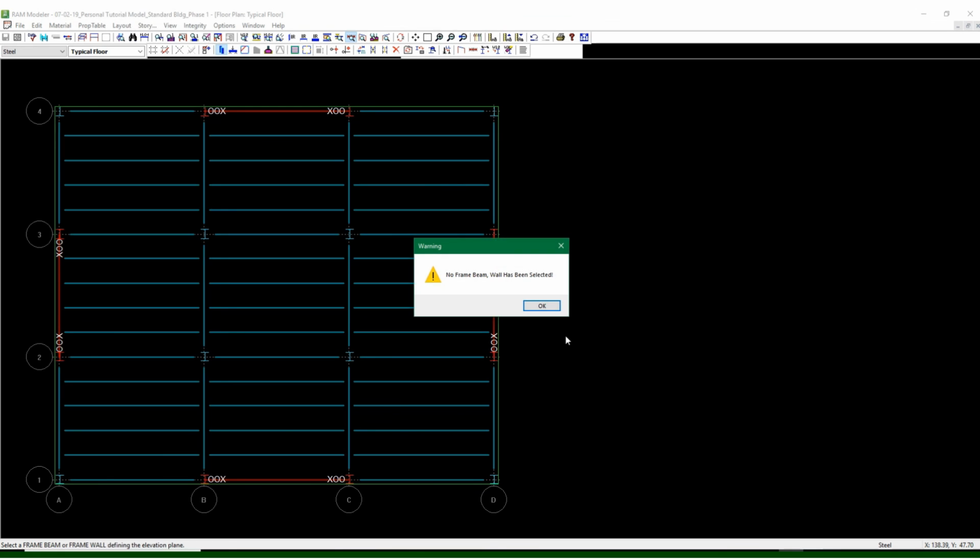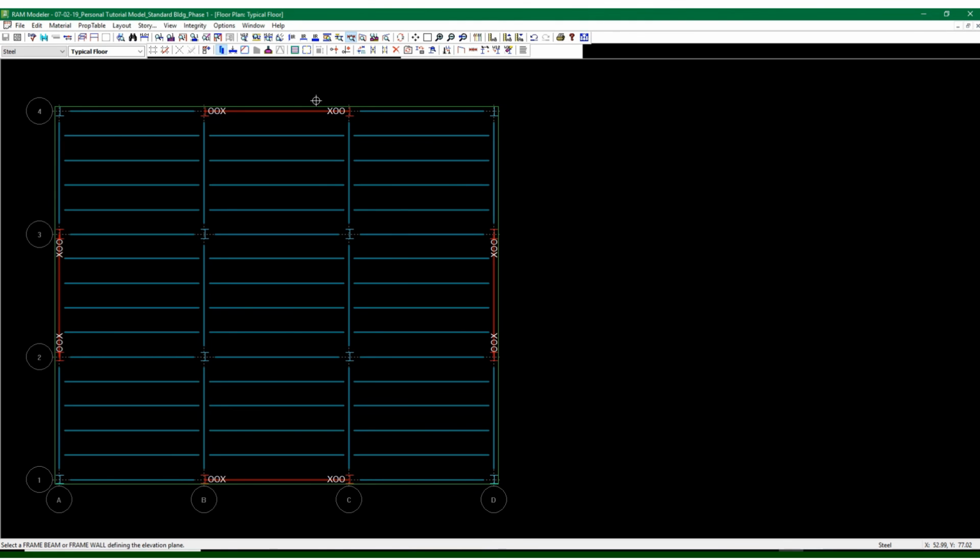So just to make sure you see the beam sizes, you say, hey, look, I didn't really pick a beam size manually, but apparently I have a bunch of beam sizes assigned to this now. What are they? I click on W12. Well, I'm sorry, this W12 icon, so to speak, just shows the sizes of the beams for all of the lateral frames. Now let's just go ahead and select some sizes for the column so we can see how to get rid of this error.